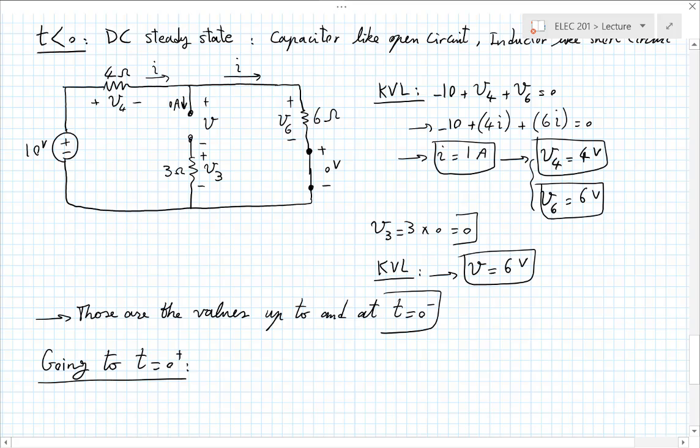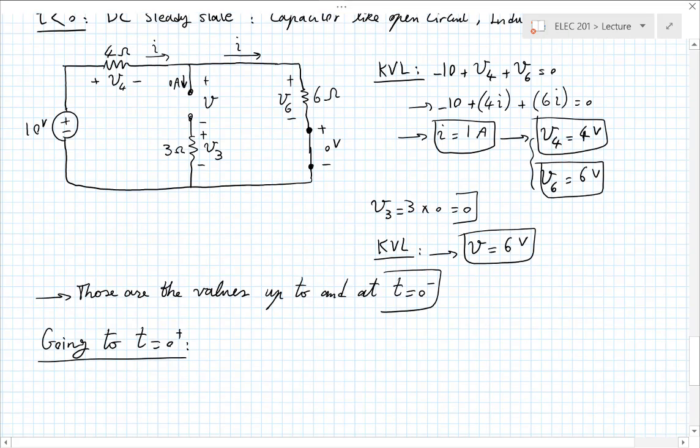again, we haven't really done anything specifically second order yet. All these things that we are talking about are a way to practice for similar situations in first order circuits too. So at t equals 0 plus, we have to identify what the things are that we can carry from 0 minus. For the capacitor, what is it that carries over from 0 minus to 0 plus? Is it its voltage or its current? It's voltage, because it doesn't like a sudden change in the voltage, right? So V of 0 plus will have to be the same as V of 0 minus.